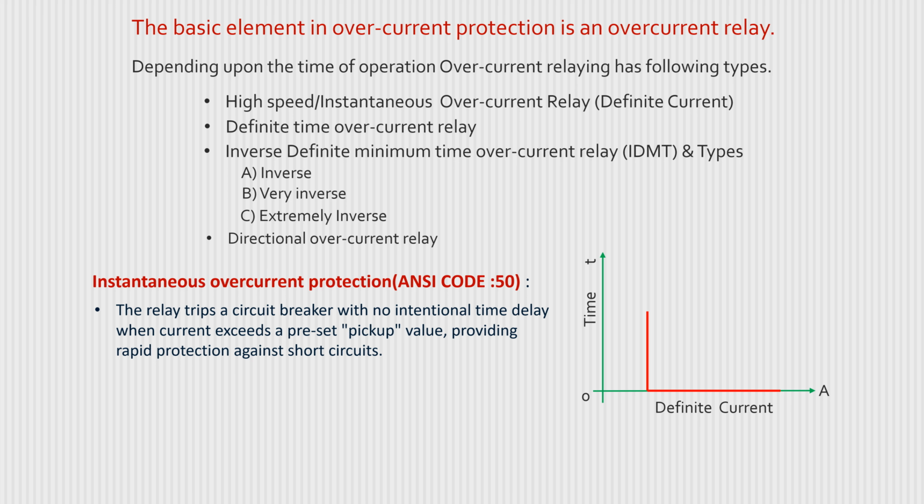The relay trips a circuit breaker with no intentional time delay when current exceeds a preset pickup value, providing rapid protection against short circuits.